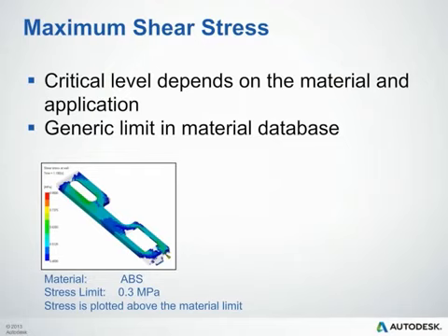If you are seeing issues with shear stress, there are a few things you can take a look at. Your wall thickness, for example. Increase your wall thickness to reduce these stresses. Your flow rate. Lower the flow rate, locally or globally, to reduce stresses. To reduce them locally, you could accomplish that through maybe using a profiled injection velocity. You can always take a look at your melt temperature as well. Increasing the melt temperature will typically lower the shear stresses as well. If you're still having issues, then you may need to reevaluate your material selection.